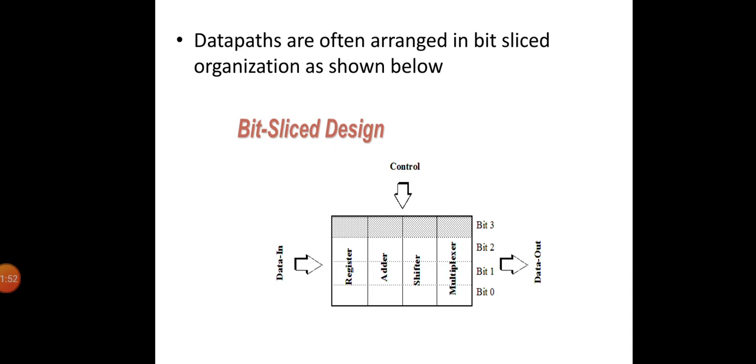Instead of operating on single bit digital signals, the data in a processor are arranged in a word based fashion. Typical microprocessor data paths are 32 or 64 bits wide, while the dedicated signal processing data paths, such as those in DSL modems and magnetic disk drives or compact disk players, are of arbitrary width, typically 5 to 24 bits. For instance, a 32-bit processor operates on data words that are 32 bits wide, and this is reflected in the organization of the data path.